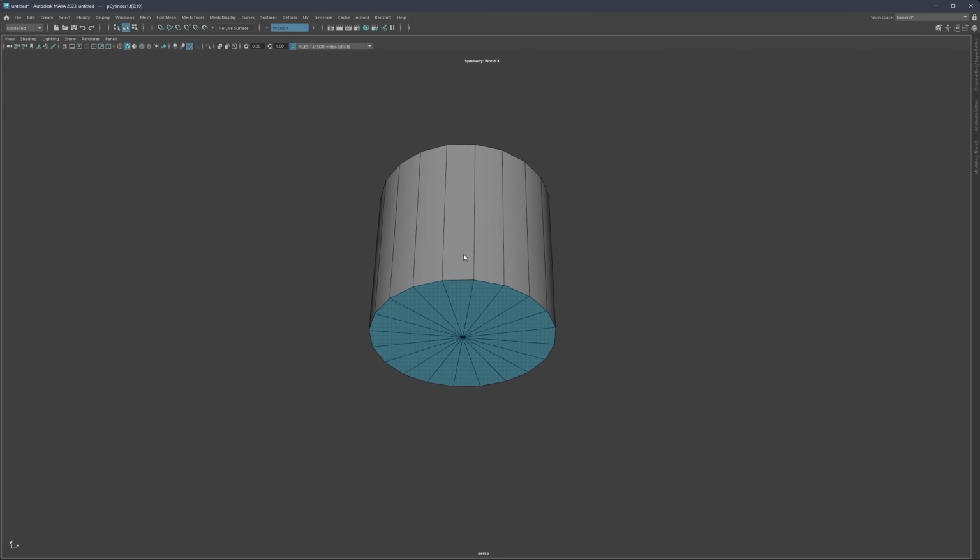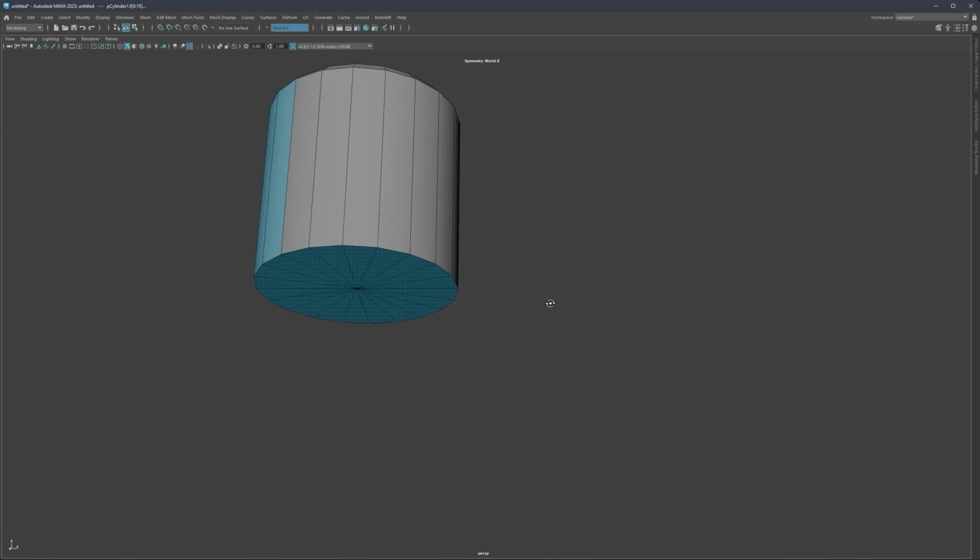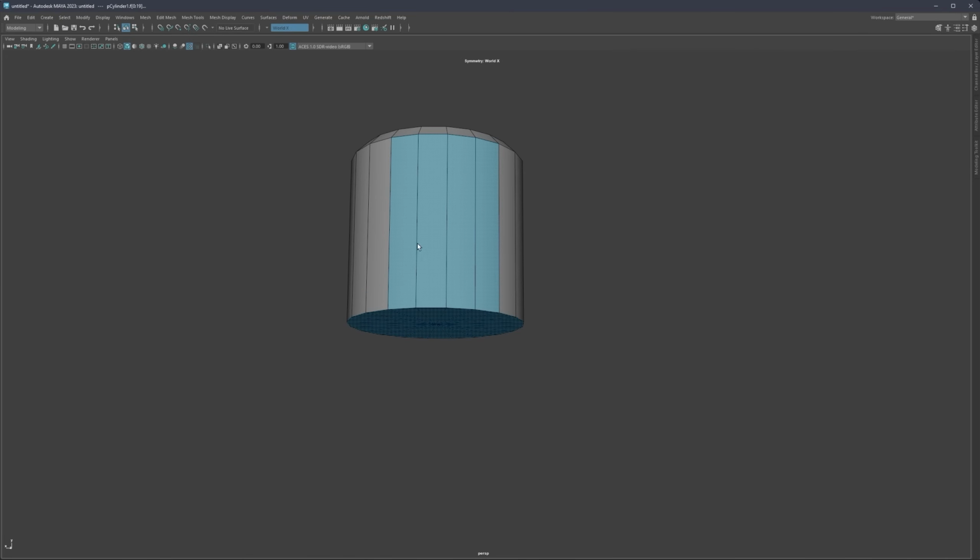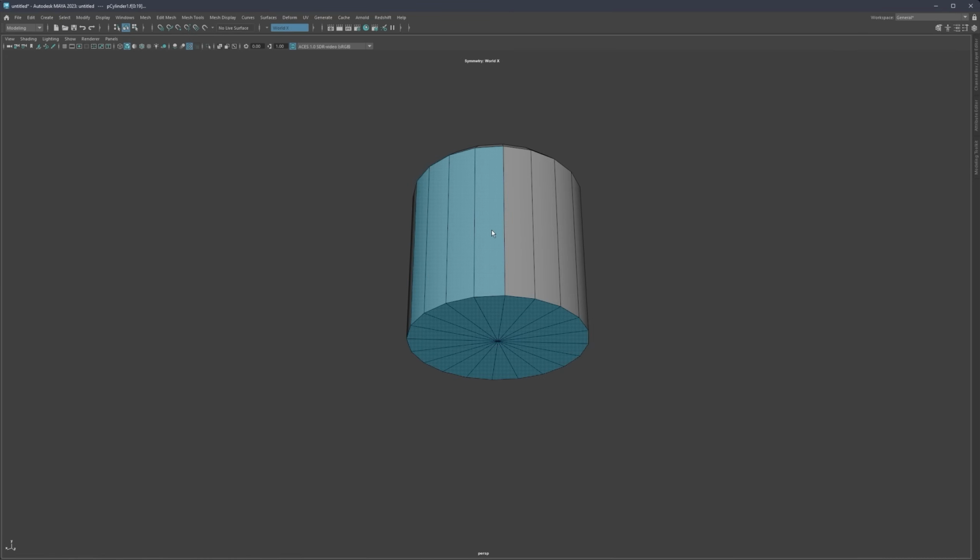So to double check on that, let's go to Shift, right click. Actually, I'm sorry, Shift, Control, right click, and then you're gonna have select and then camera based selection. Just make sure that this is checked on. If this is checked off and you're selecting parts, then that means that you might also select something on the back. And if you don't want that, again, Shift, Control, right click, and camera based selection.